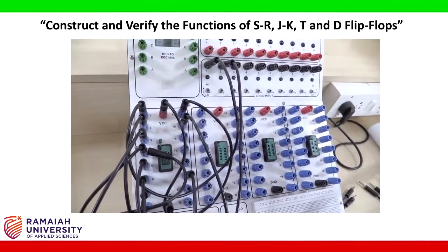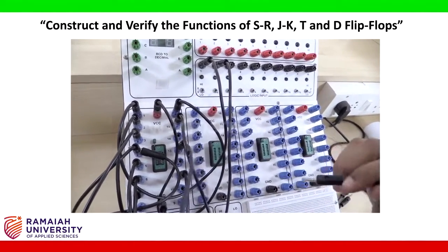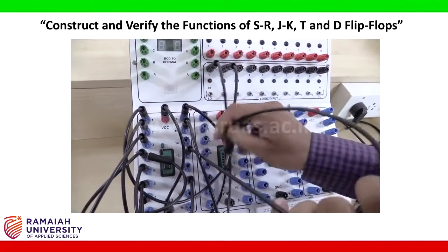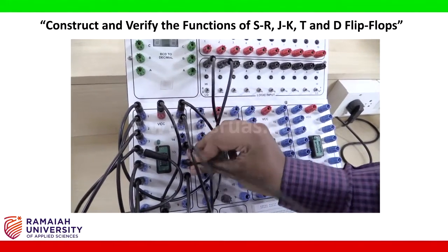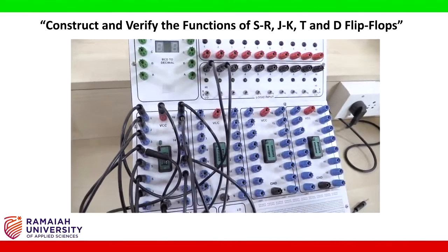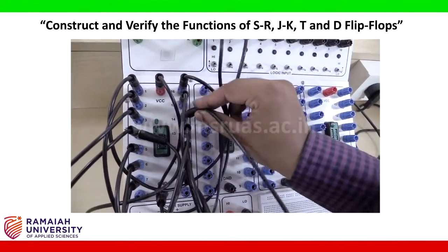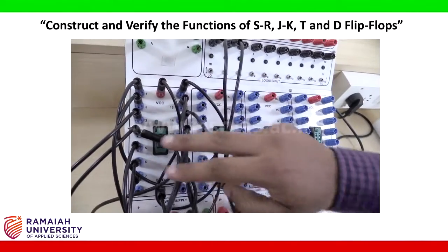Next, pin number 10 is connected to pin number 11. So 10 and 11 are shorted. Pin number 8 is connected to pin number 12. Now this completes the inputs.